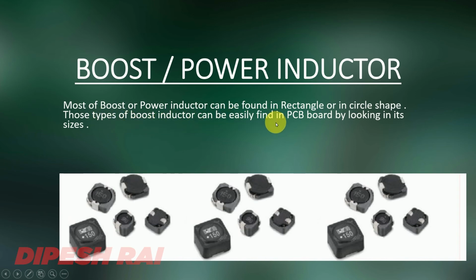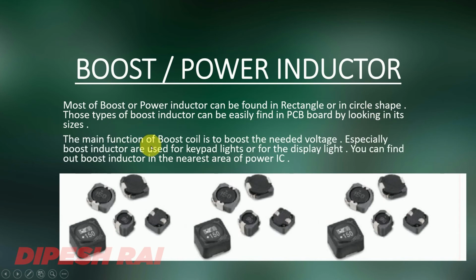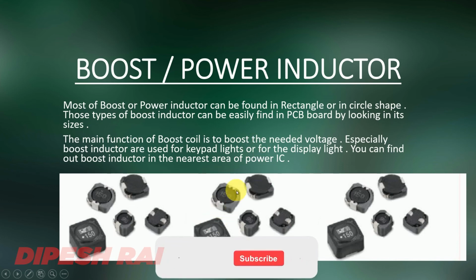The main function of the boost coil is to boost the needed voltage. Especially, boost inductors are used for keypad lights or display light. You can find the boost inductor in the nearest area of the IC. In most cases the boost coil can be found near the power IC, because it helps us to boost the power or voltage. That's why it will be in the nearest area of the power IC, so you can check there for this kind of boost coil.